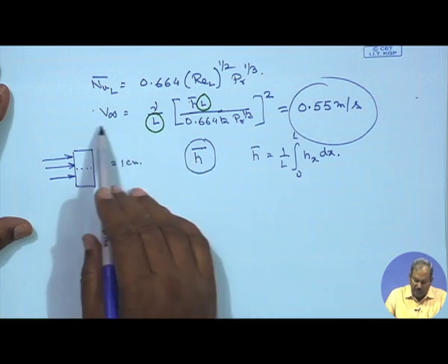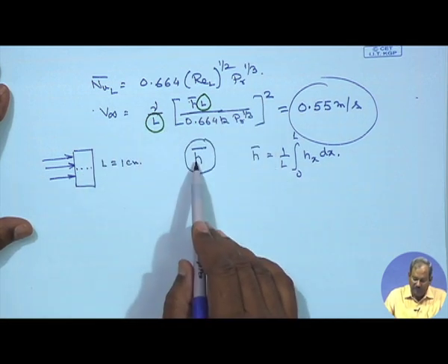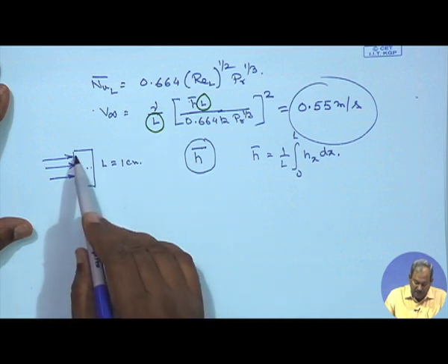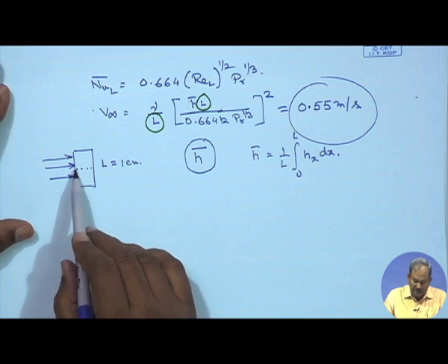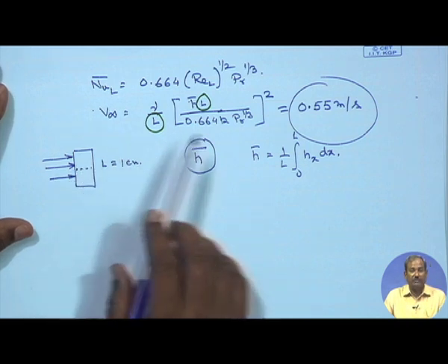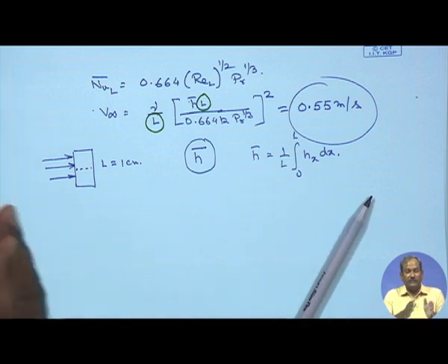And what we are using in these correlations is the average value of H. So, unless this material has a high thermal conductivity, there would be local variations of temperature on the chip. Since I am basing all my calculations on the average value of the heat transfer coefficient, I understand that the value of local heat transfer coefficients can be different at different points.